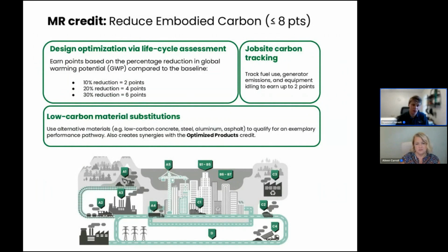And in terms of what options are available to you, there'll be usually regional constraints in terms of the different mixes, different steel that you can procure for the project, but looking at things like using alternative binders in that concrete or using steel from a plant that has optimized its furnaces to be electric can go a long way with going after the low-hanging fruit, we'll say.